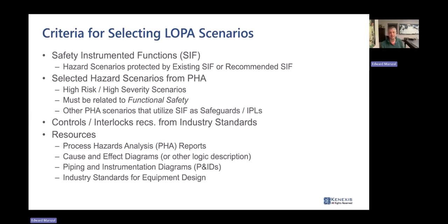Those of you that have talked to me before, have been in my training classes, know that I come at hazard and risk analysis from the perspective of an instrumentation and control engineer, as opposed to the perspective of a process safety management practitioner. So my objective when I'm going into the hazard and risk analysis is, there is a collection of equipment that I need to design. So I need to set performance targets for that equipment to allow me to perform that design.